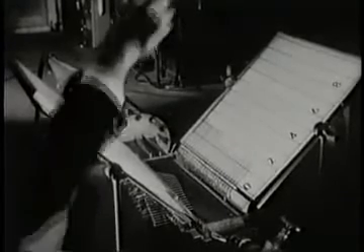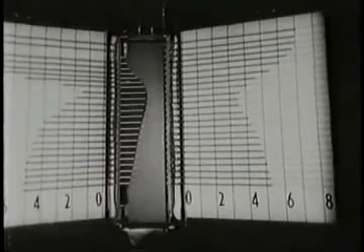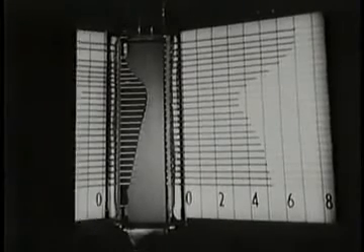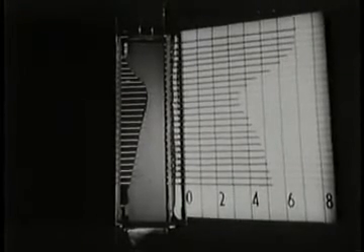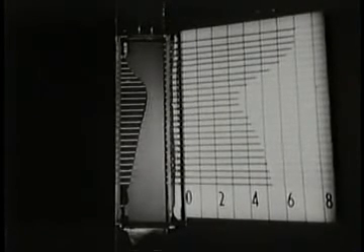Now the flow is steady. We will look first at the pressure distribution on the straight wall. Continuity tells us that because of the area contraction, the velocity increases to the throat, and this causes a pressure drop.